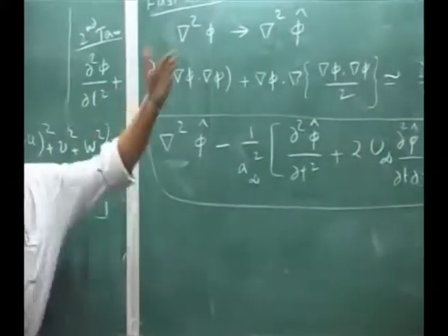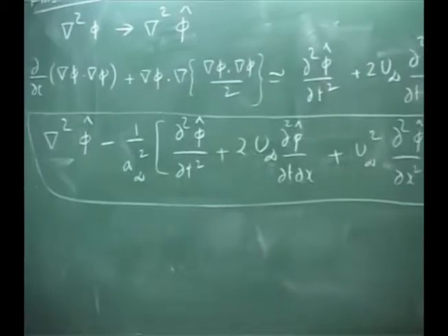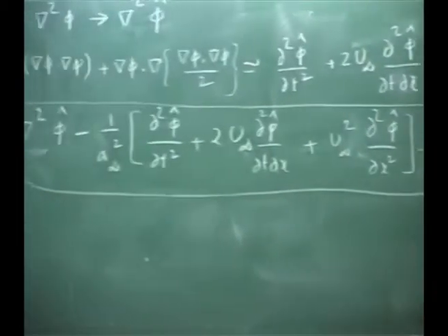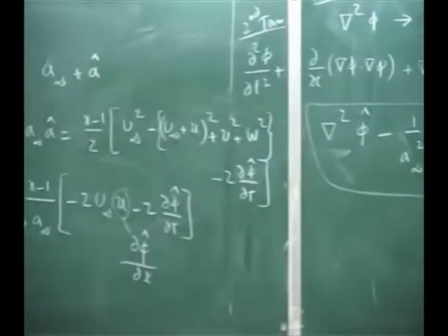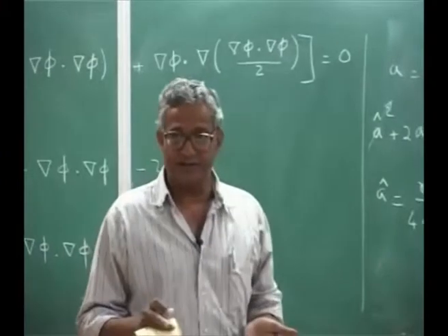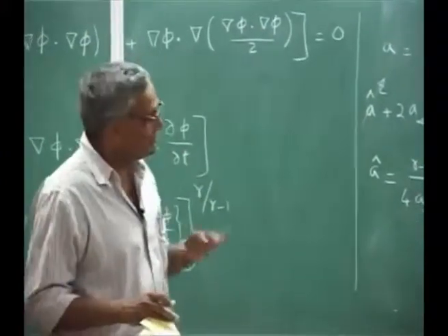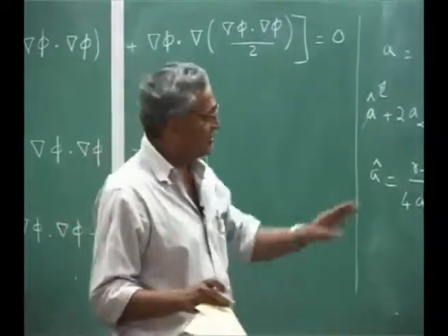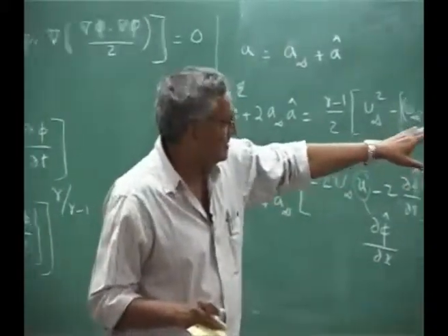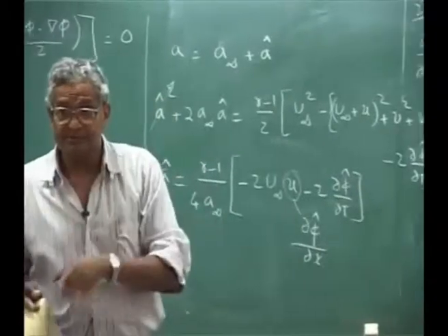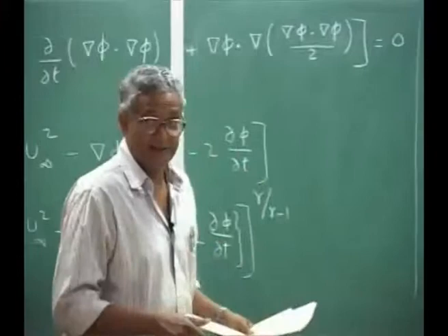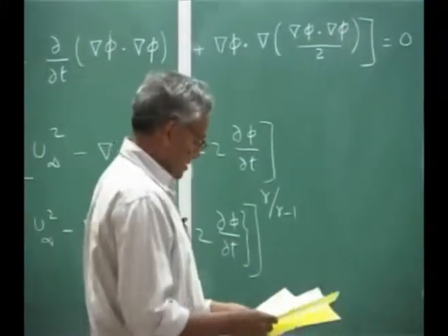We are not going to use some other, because we say so long as the Mach number is not very large, below Mach number 3, because there are other problems, heating, local heating, everything will come. We have isentropic flow, we made isentropic flow as an assumption. Based on that assumption we say up to less than Mach 3, these equations are fairly good. And that's why these are used, potential flow, small disturbance.